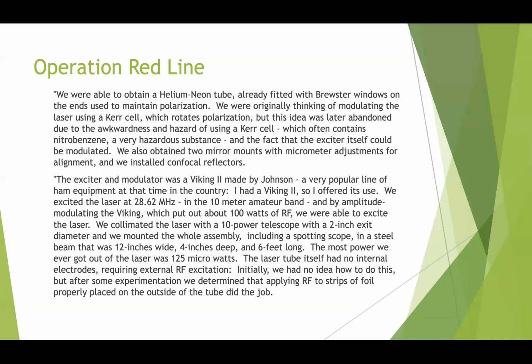The exciter and modulator was a Viking 2 made by Johnson, a very popular line of ham equipment at that time. I had a Viking 2, so I offered its use. We excited the laser at 28.62 megahertz in the 10-meter band, and by amplitude modulating the Viking, which put out about 100 watts of RF, we were able to excite the laser.